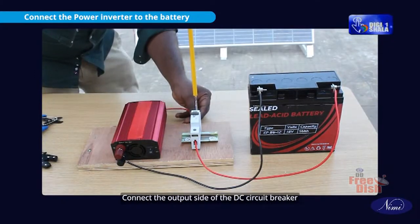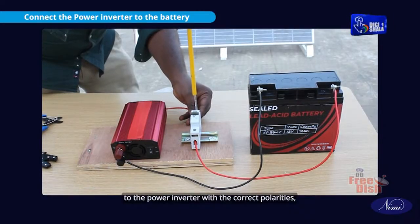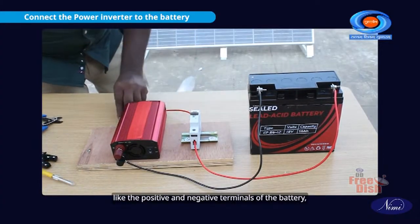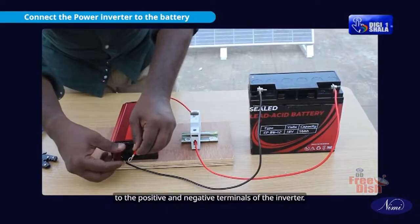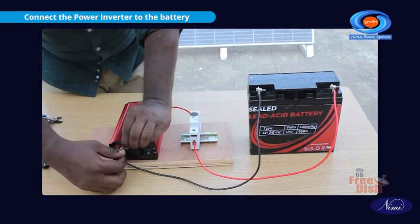Connect the output side of the DC circuit breaker to the power inverter with the correct polarities, like the positive and negative terminals of the battery to the positive and negative terminals of the inverter.